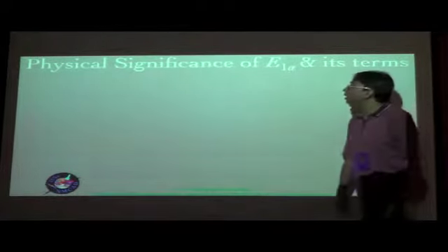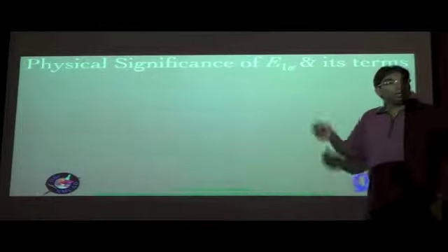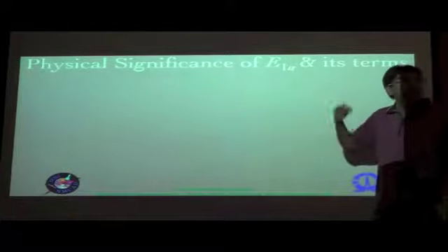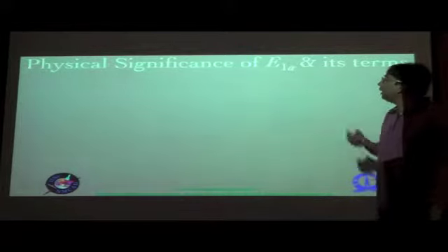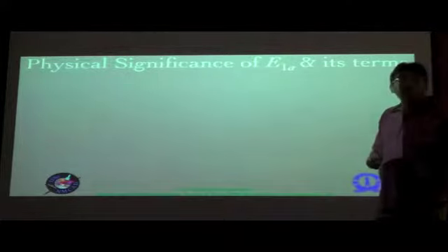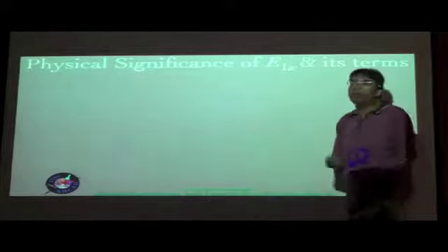So next, let's look at the two terms E12 and E13. Of course, we saw that for that simple example, E22, E23 and E33, these are the strains in the cross-section, are all zero, because of the fact that we assume W2 and W3 to be zero. So the only three strains of interest are basically gamma 11, gamma 12 and gamma 13. So gamma 11 we already looked at. Now we look at gamma 12 and gamma 13, for which E12 and E13 are the leading terms.